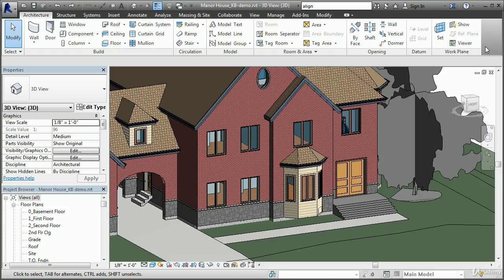There are many advantages to working with a BIM approach. Probably the most significant benefit is that developing a single building model as the basis for all related construction documents ensures coordination between different views of a model. When you delete a window in a plan view, this change will automatically be applied to the elevation views as well. The window schedule will also be updated at the same time. Any changes made to the model in any of its views will seamlessly and automatically be propagated to all other related views.